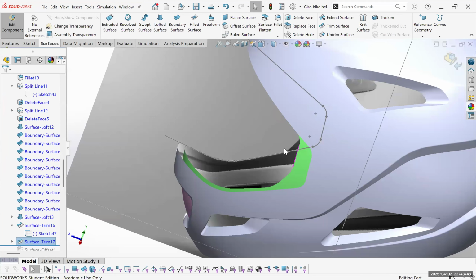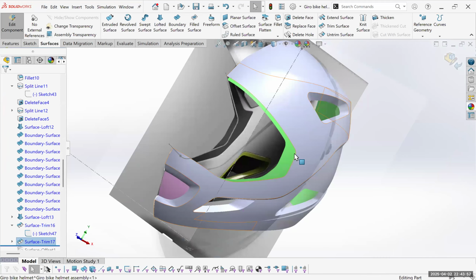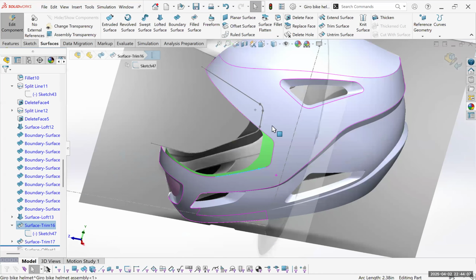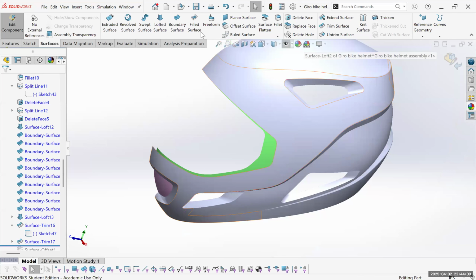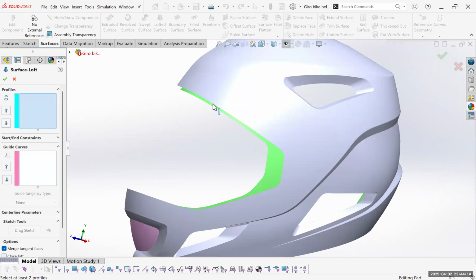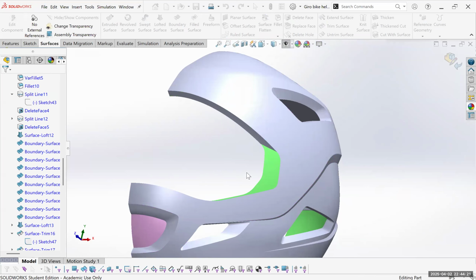We can just loft everything. We can connect our flats together, then flat here together. Here, where we have this, then it turns into that. We need to section it off and boundary it off that way. I'm just going to remove all of those so it's easy to see. Do a quick loft from here to here. Okay, that's simple.